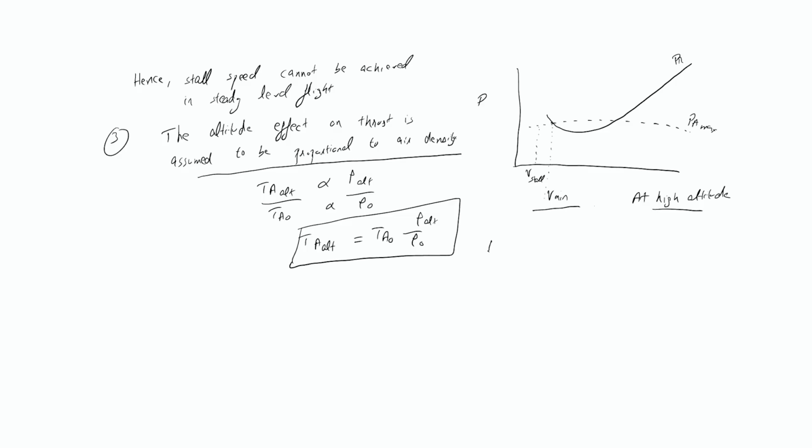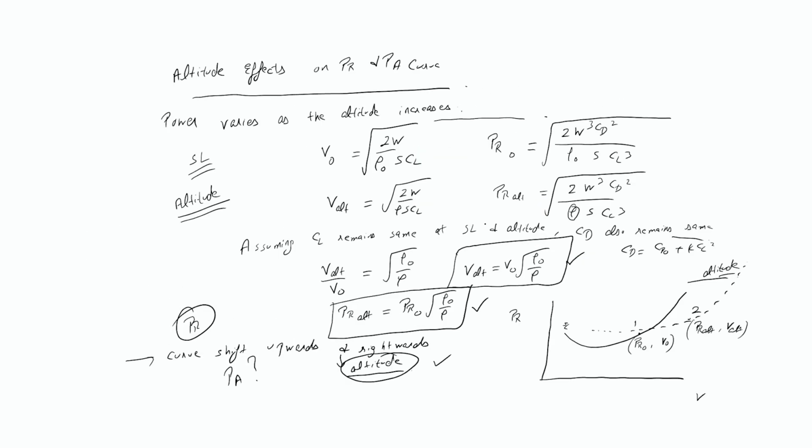Similarly, power available at altitude equals power available at sea level times rho altitude upon rho naught. All right, so these are the three points that needed discussion.